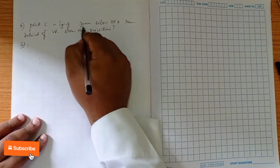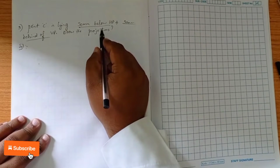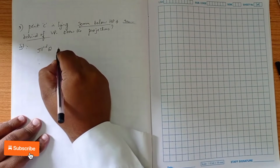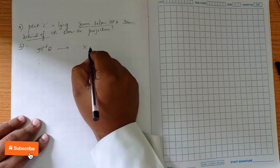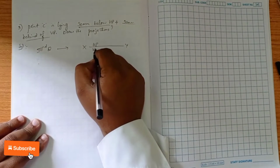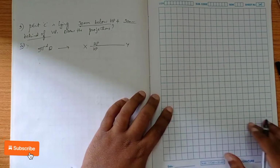We need to identify the quadrant first. Below HP and behind VP means this is the third quadrant. Now we have to write the convention for the third quadrant. HP will be above the XY line and VP will be below the XY line. It is nothing but the reverse of the first quadrant.